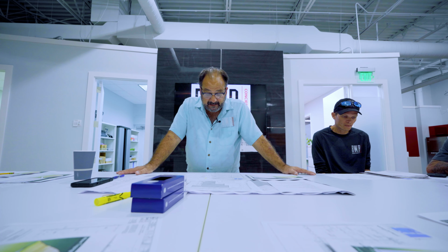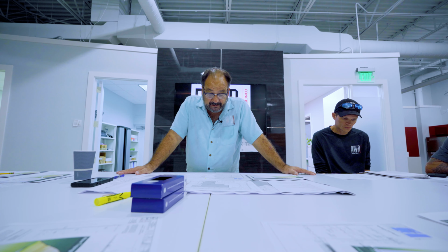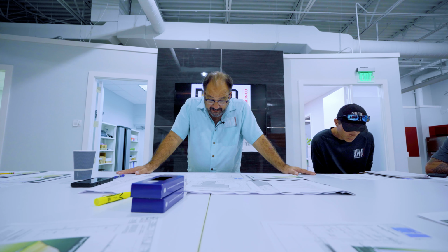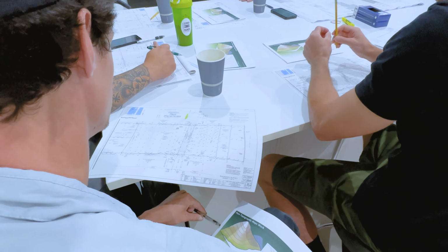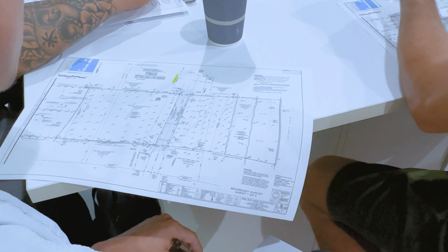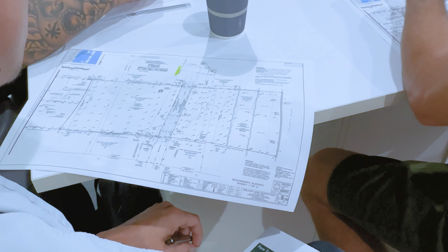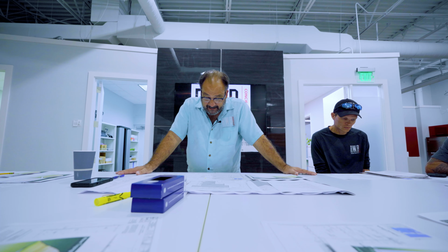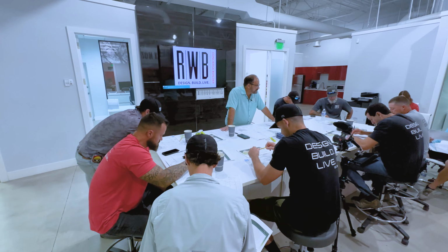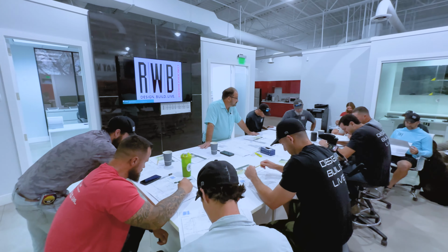Okay, if you look at this plan, it does show a fence along the north side of the property. It shows a site wall on the left, on the bottom, and you will see certain terms on here so you know what they mean. For example, TOW is top of wall. So if you look at the bottom of the page, you'll see an existing wall that separates the two properties. All the points you see here with numbers, these are all elevations, okay? So the surveyor goes out and periodically in a grid, he measures all the elevations.